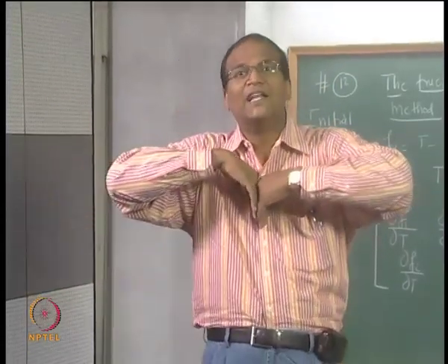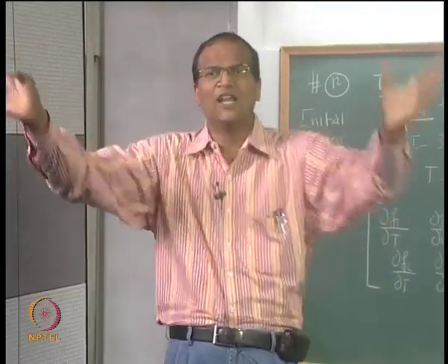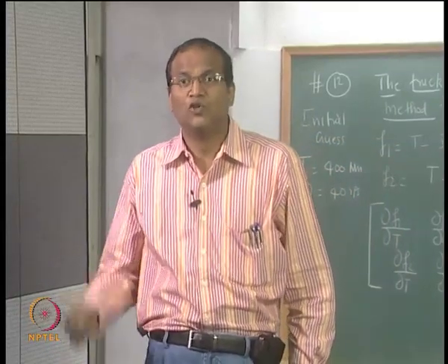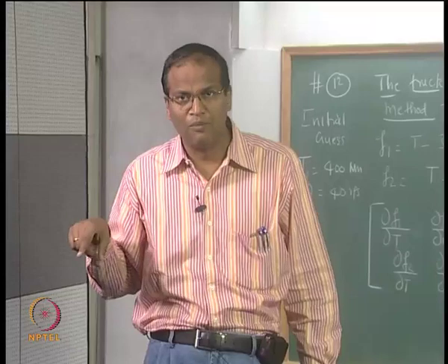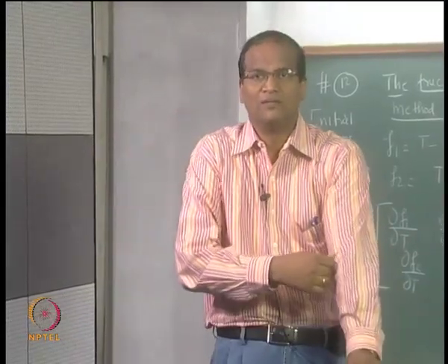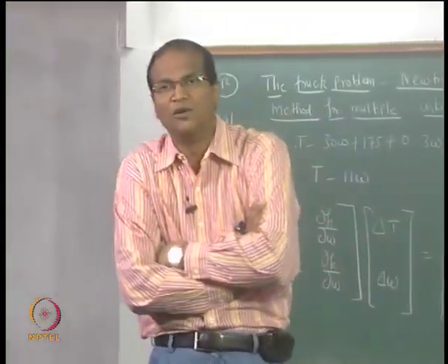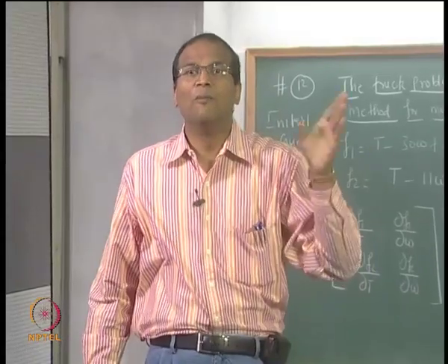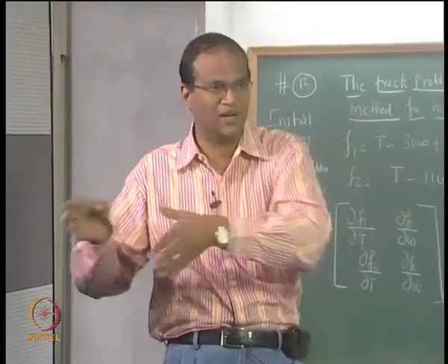Okay, it is converged, but you converge to a highly inaccurate solution. So we need additional checks. What do you do normally when you are solving a heat transfer problem? I will ask my students to check whether the energy balance is satisfied. If it is steady state, whether the sum of energy in is equal to energy out. If it involves mass flow, mass in minus mass out divided by mass in, modulus, into 100.